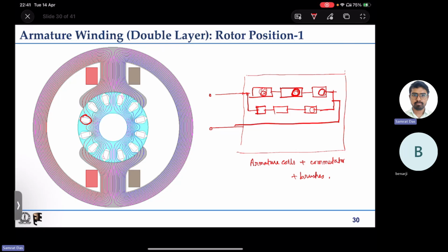But if at any instant of time, if we go instant by instant and get the equivalent induced EMF for the circuit, then we'll find out that if we try to model the entire thing, it could be perfectly modeled with some constant resistance, some constant inductance, and some constant induced EMF that is only dependent on speed.